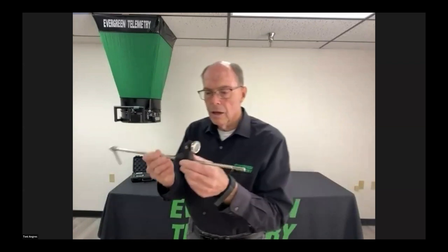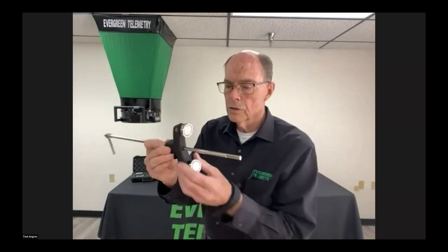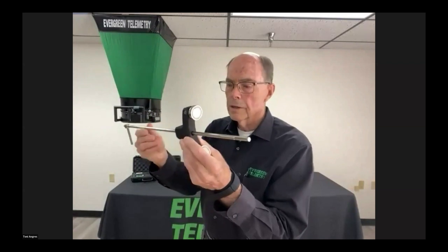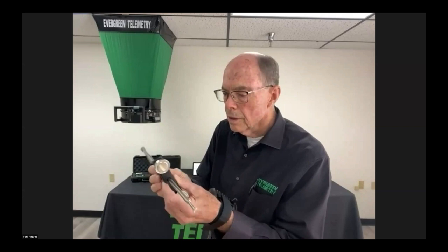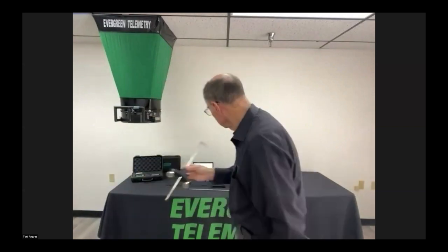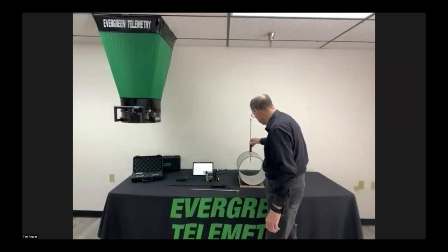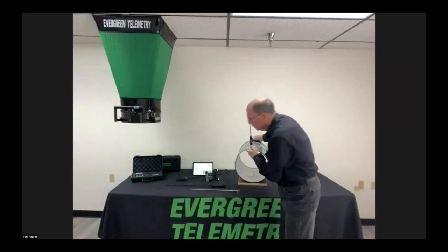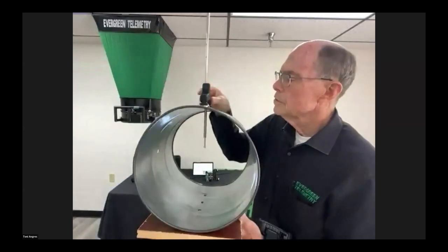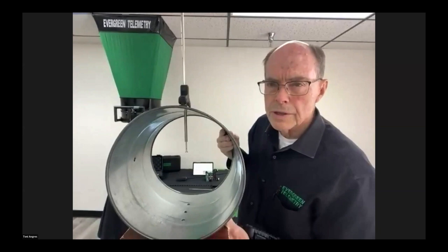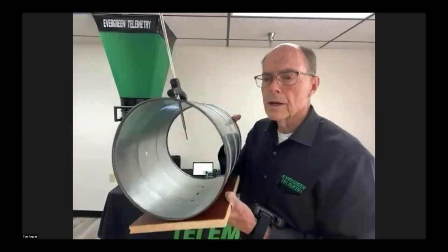One is what I call the guide lock. It's got 2 purposes. One is so that when you're doing a traverse, you'll be properly oriented and the tip won't be wavering around. But the other is, imagine that you are going to make a change to a fan or a damper in order to affect a change in the CFM. What you can do is set this up like this. I'll hold the duct up a little closer so you can see. Basically, set the probe up to get a center line of velocity.